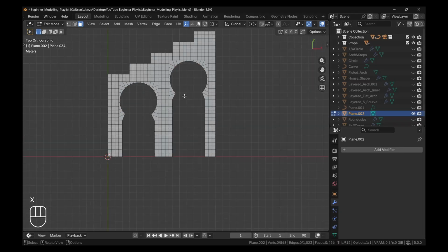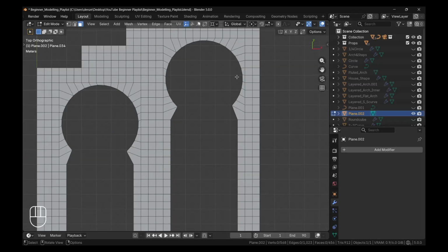And we should have what looks somewhat like a keyhole. Now we're going to fix that because you see these middle vertices here. Actually, this is supposed to be straight so that way we could be able to line it up properly. And I could do that. So press 1 for vertex select. And we notice that this line here is straight. So we could use this as a marker.